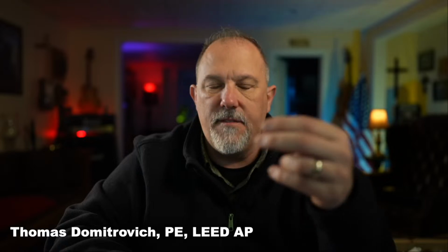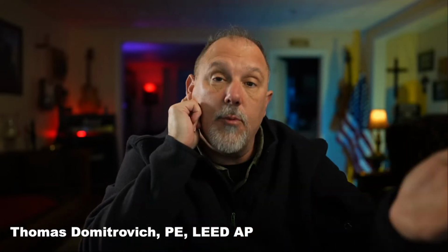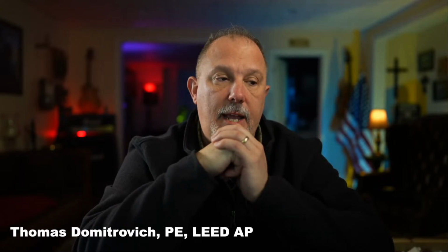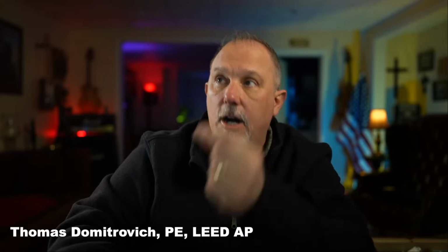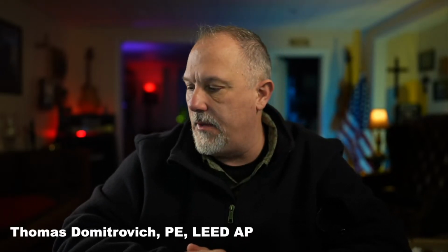Now, just because you see some of the venting doesn't mean that the breaker is no longer functional. It doesn't mean that it didn't do its job. It doesn't mean that you need to replace it. I would argue that you probably want to do some preventive maintenance on it, and I would reference this NEMA AB4 document to give you guidance on what you can and can't do with a molded case circuit breaker. You don't want to be taking it apart at all to look at those arc chutes and contacts and all that. I know it may be tempting to do that, but that would not be a good thing.